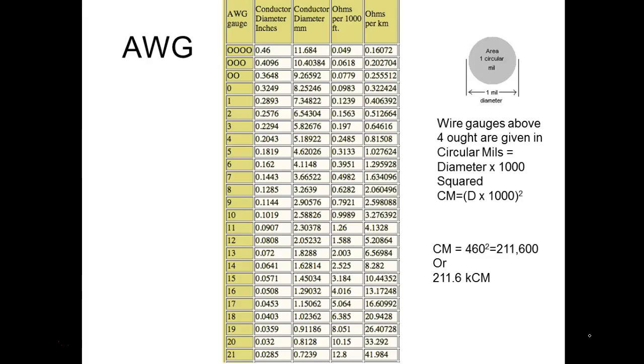Well, and so what we end up with is we end up with this little chart right here, with the last column. So when we give out wire gauges, wires are gauged, and this is called the American wire gauge, and this is the gauge that we'll be using. We also have the European wire gauge, which uses millimeters. Some of your wire gauge charts use both. This one does, in fact.